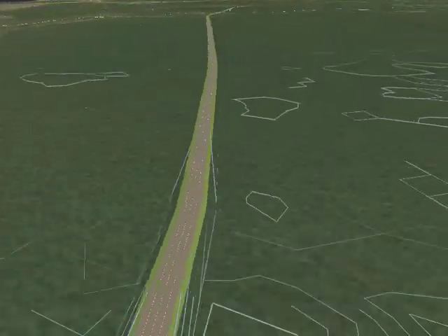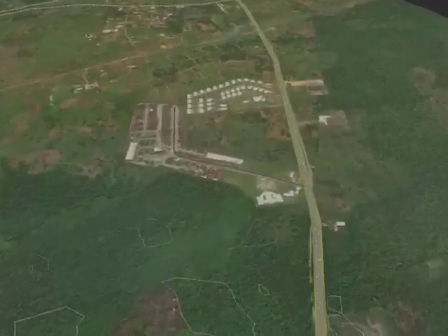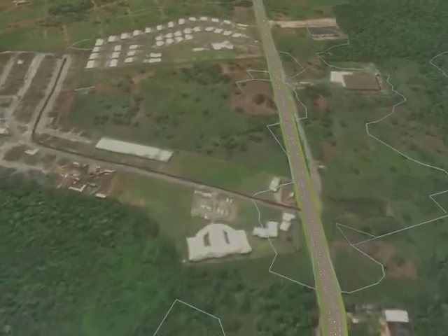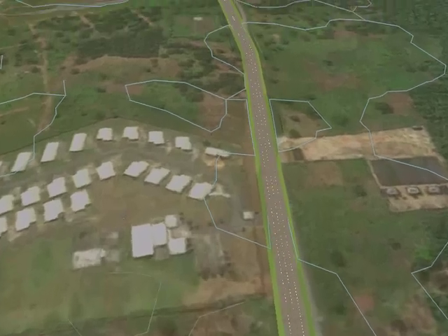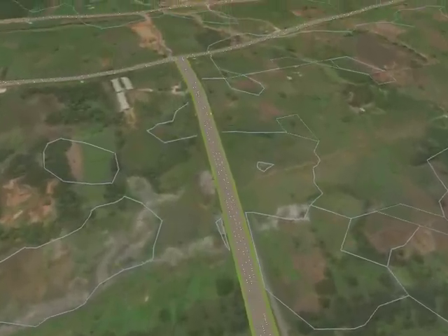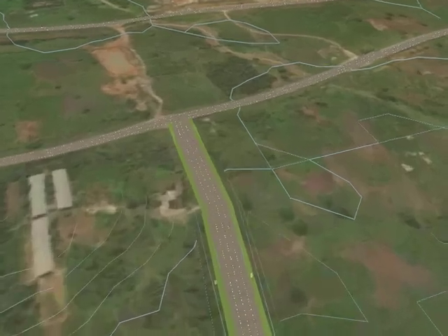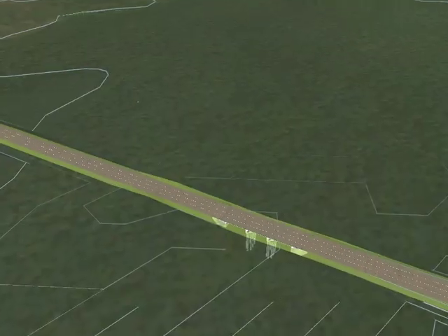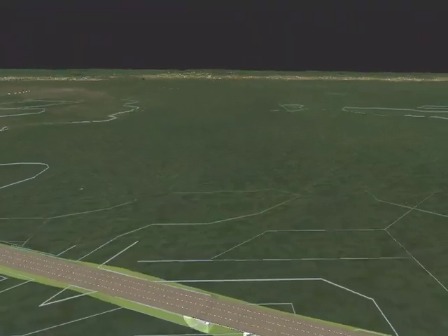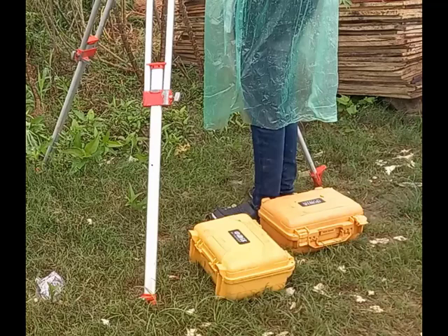In most cases in schools in the past, what engineers have been taught about surveying centers around how to take levels, forward side, back side, as well as to do traversing in order to create a map. But when you are talking of topographic survey, you are talking about a map area of which the elevation and coordinates have been identified and ascertained with data acquisition. In this video, we are going to look at how a topographic survey can be done by data acquisition using a GNSS receiver and device in order to establish the elevation of different points in that location.